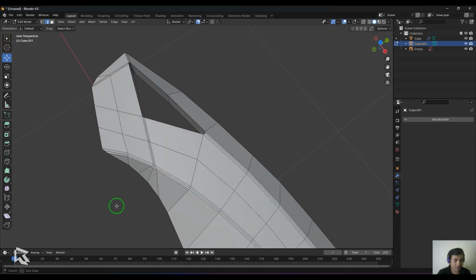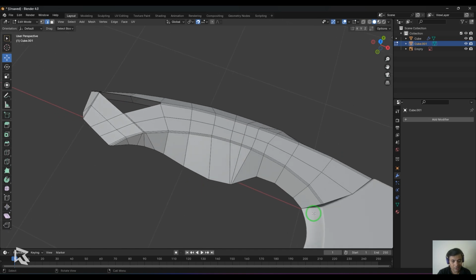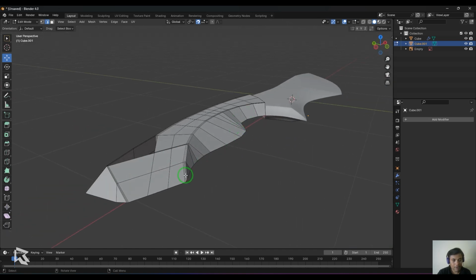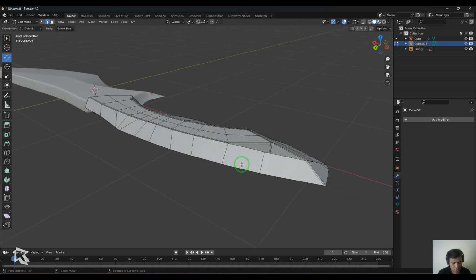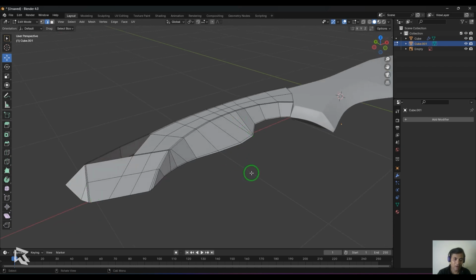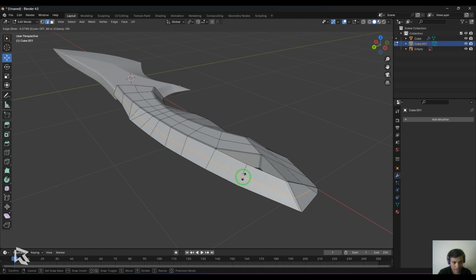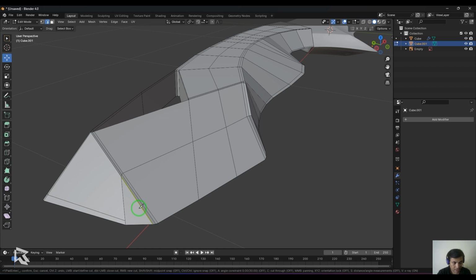So that adds the crease along that particular hole there. Now once that is done, I need to add a line which runs across the border here. So I press Ctrl R and make sure that this is at the border here. I press Ctrl R, or if I don't do that, this will turn out to be a round. That also looks good, but let's keep it sharp only. Here this line has to be connected, so I press K and start connecting those lines there.